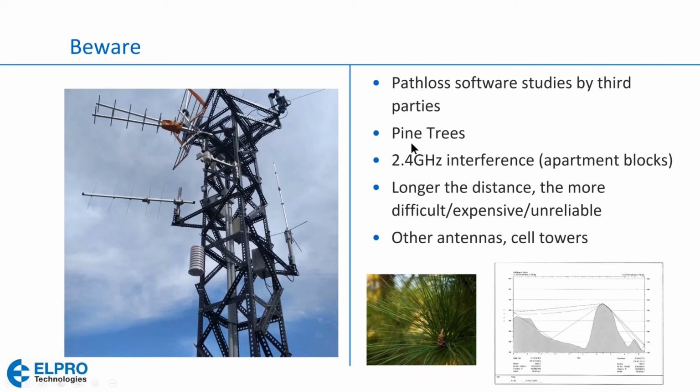For 900 megahertz radios, be careful of these types of pine trees. I'm specifically referring to the type of pine trees that have the 3-inch long needles. They resonate at 900 megahertz, just strictly by coincidence. I think they're called ponderosa pines, but don't hold me to that. The ones with about 3 to 4 inch long needles represent a much more dense obstruction to 900 megahertz only. One pine tree is going to be the equivalent of about 5 regular deciduous trees.